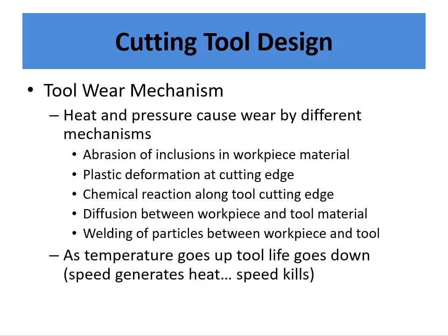So essentially the chemicals in the tool to the workpiece or vice versa can leach into one another, or you can leach them out of the tool, or the material in the workpiece can actually leach into the tool and break it down, and then it wears out. So both heat and pressure are generally the issues you're going to have.